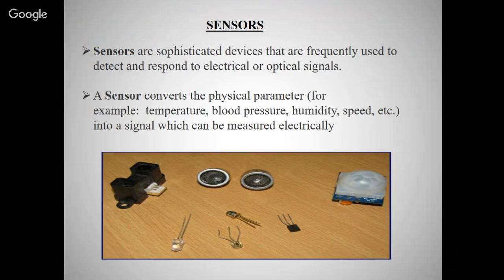We have used the LDR sensor with a potential divider circuit, a 10k resistance with the LDR, and the output is taken from the combination, from the potential divider. You can check the output from the potential divider and it is read by the Arduino.